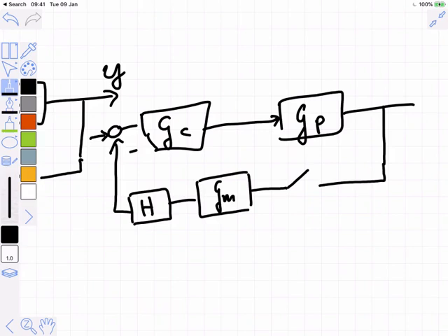You know, effectively we've got a sampled signal, and you can see how you could arrive at this place where we had maybe an analog controller and an analog process, and somebody said, well, there's this snazzy new measurement equipment. It's digital. It's much more accurate than the previous one. There's just one snag. It only does a measurement every 5 seconds. So if you just took your analog measurement out and you put this new digital measurement in, that's what you would get.